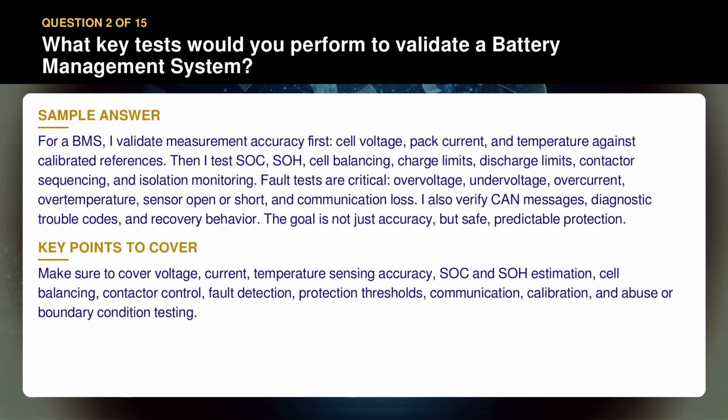Make sure to cover voltage, current, temperature sensing accuracy, SOC and SOH estimation, cell balancing, contactor control, fault detection, protection thresholds, communication, calibration, and abuse or boundary condition testing.